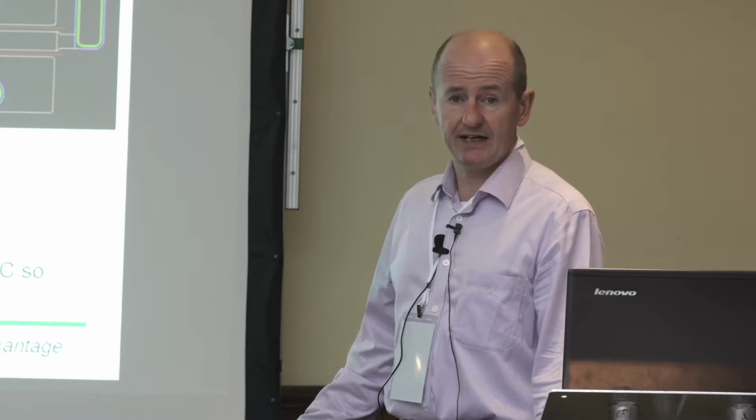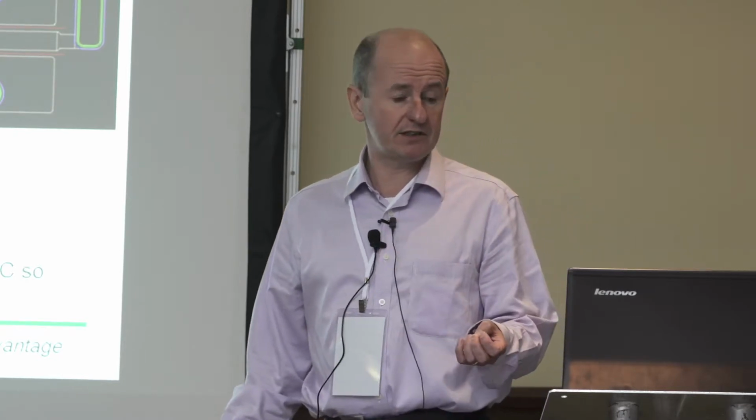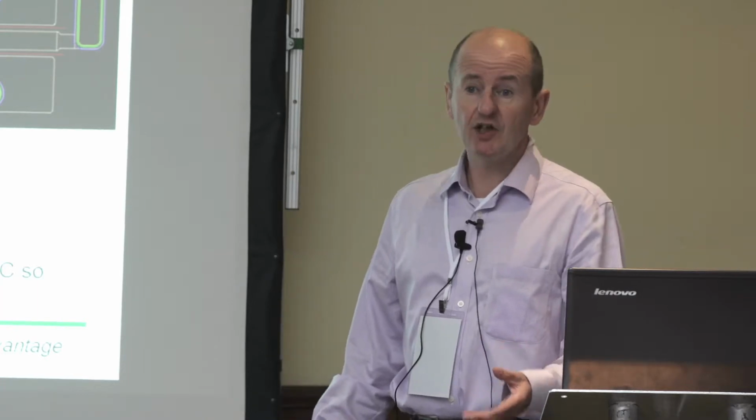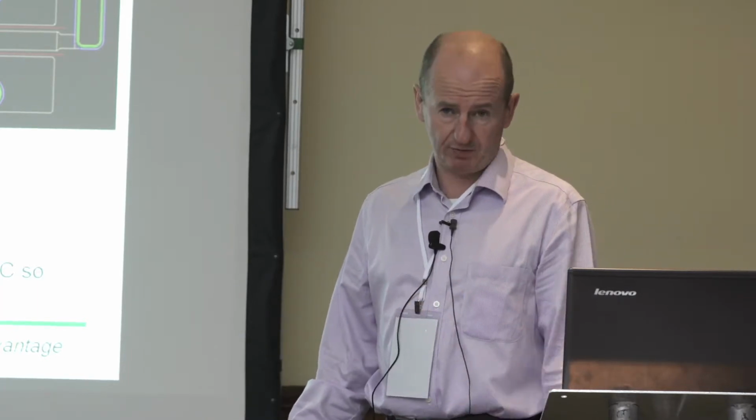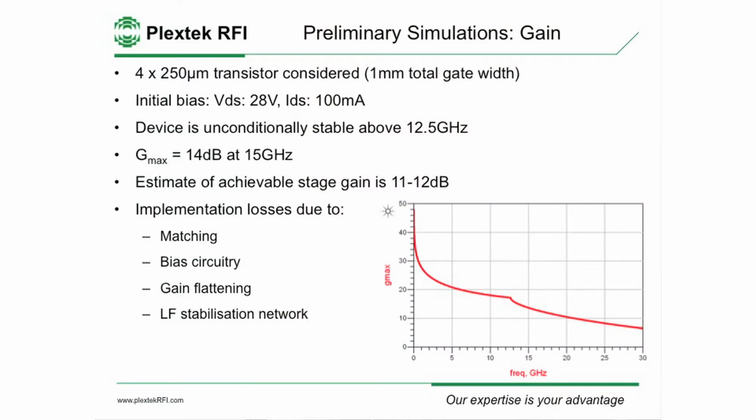And that's because of this effect. It's very important to consider and understand when you're designing a gallium nitride IC: you as the designer are responsible for ensuring that the thermal performance is adequate. And if you get it wrong, then your reliability will suffer.